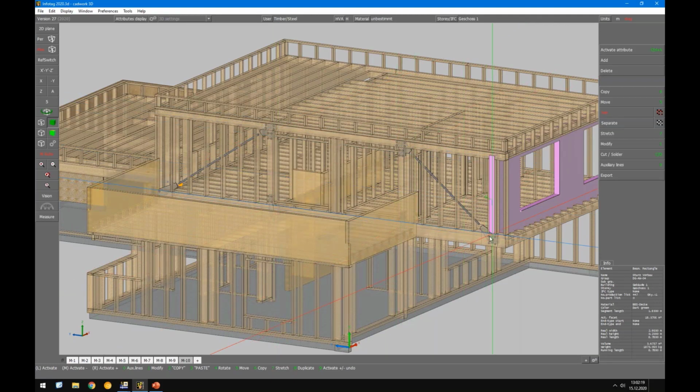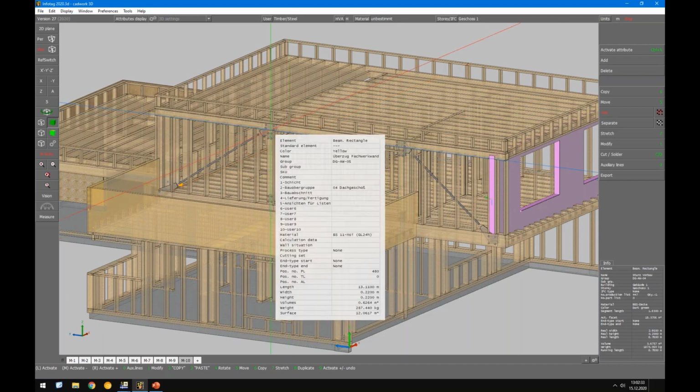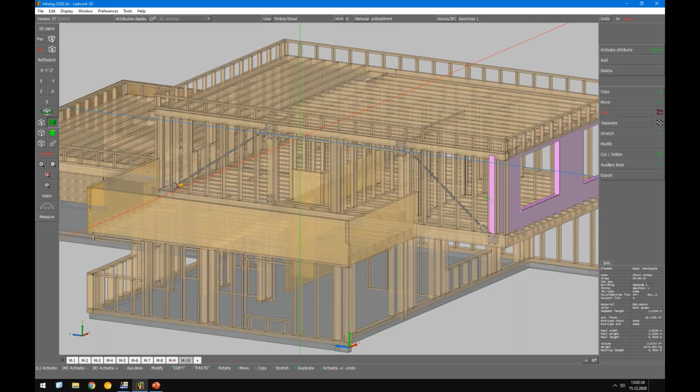So we have beams and dowel type connection. We get one component here in the vertical direction via this column, and one component goes in the upper chord to the next tension beam and downwards. So I'm interested only in